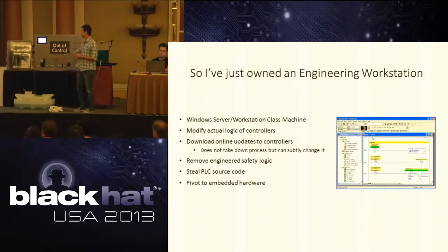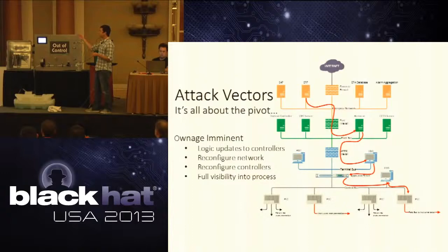That picture up there is of an engineering workstation program, and we'll talk about this a little bit later, but the language that you write on these PLCs is not C or anything like that. It has a couple of different forms, but primarily what you'll see is what is called ladder logic. You can see obviously why it's called that, but it's essentially an old programming language that's relay logic. So it's meant for electrical engineers, not so much programmers. But if you're on an engineering workstation, you can actually steal the source from the controllers themselves. You can get the logic files and modify the logic files on the PLCs while they're still online.